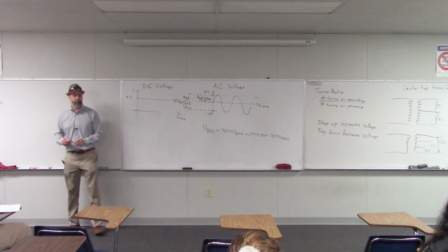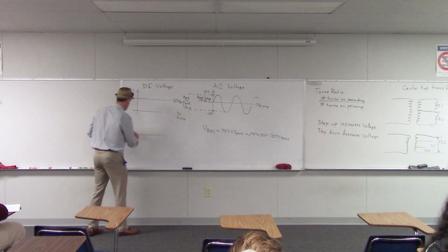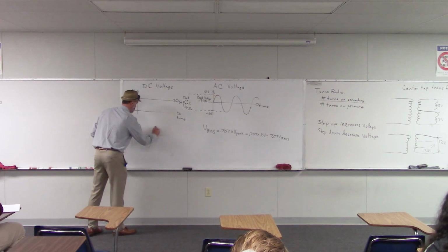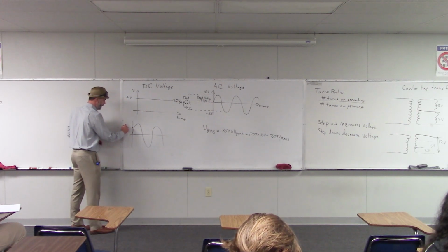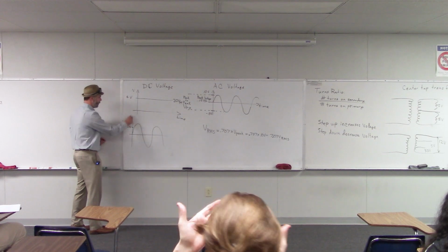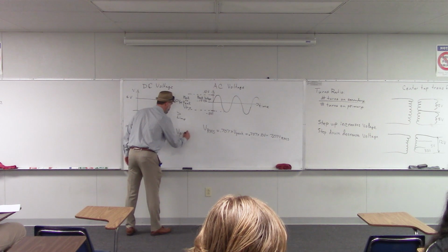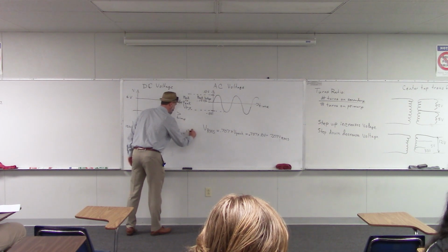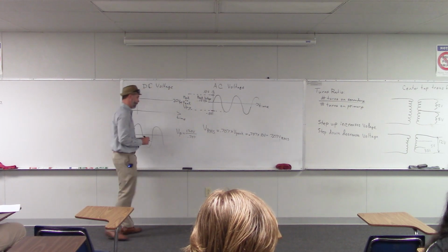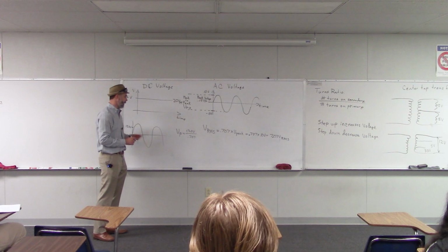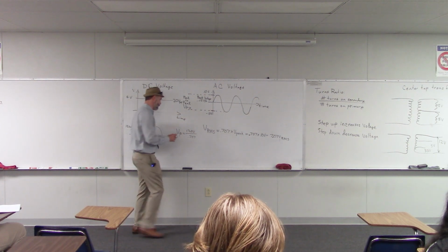So what that means is that right there on the signal is about 120 volts. So the peak voltage would be V peak is 120 volts divided by 0.707. So it's something like 185 volts peak.